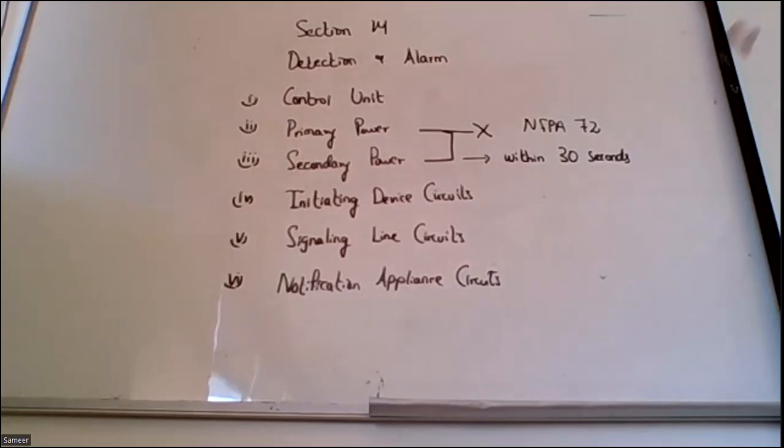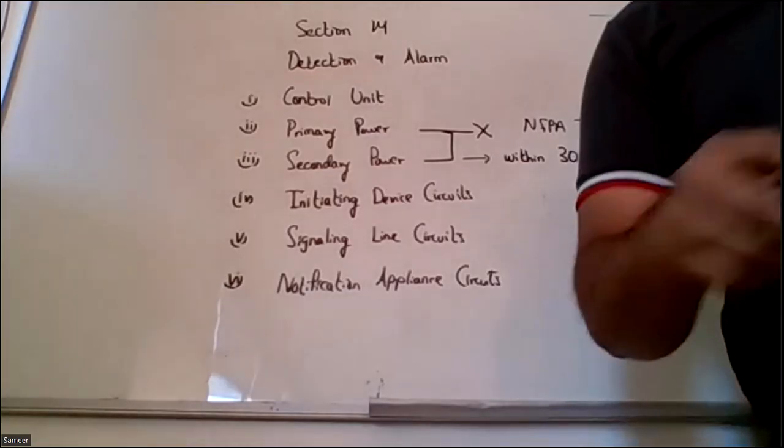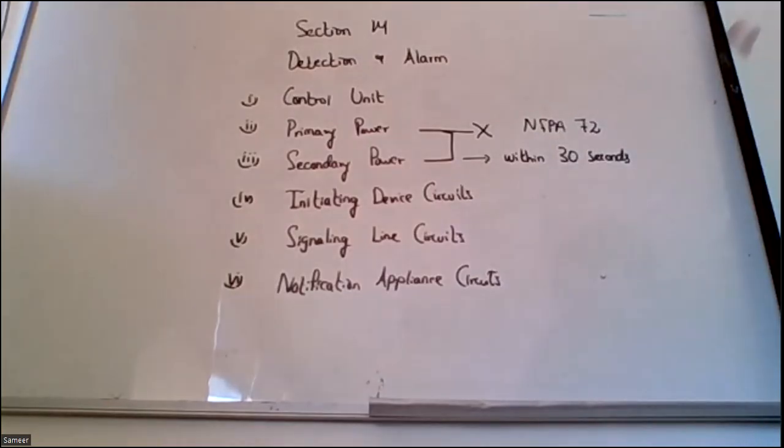Usually in the fire alarm control panel, what is our secondary power? Batteries. Why is it 30 seconds? Why is this clause there for 30 seconds? The battery will shift power in milliseconds, right? Why 30 seconds? NFPA 72 says within 30 seconds.